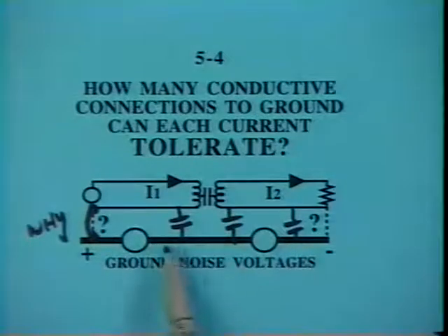So there is going to be a slight amount of current from the grounding system circulating up onto the signal path. But again, assuming that the ground noise voltages are at low frequency, and assuming these capacitors are not that large, maybe the amount of circulating ground current is allowable. We'll assume that it is in this case. So I think we could get away with this.